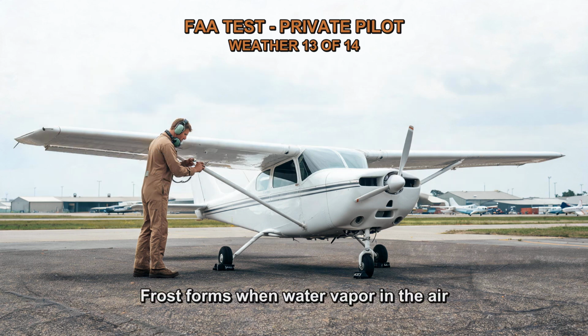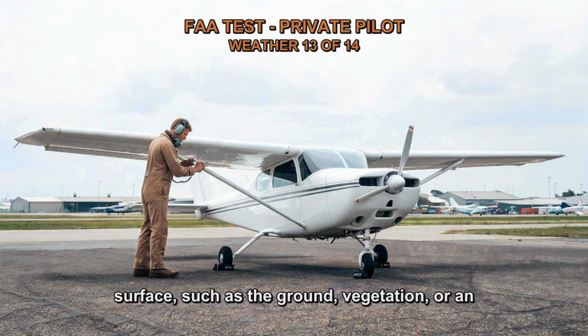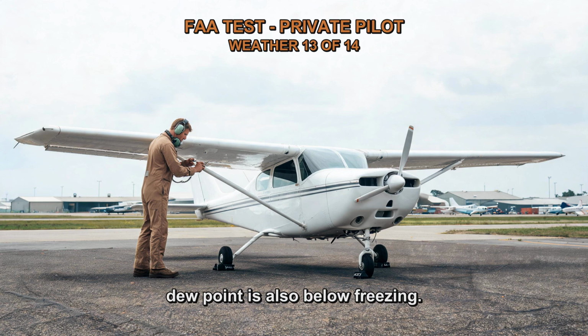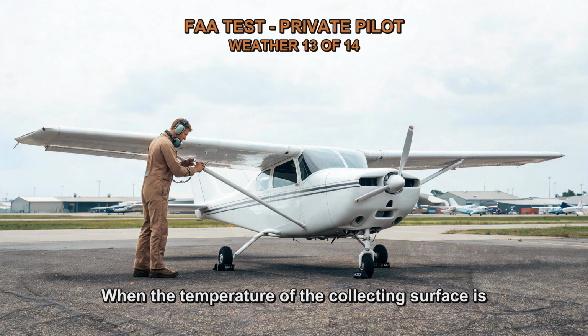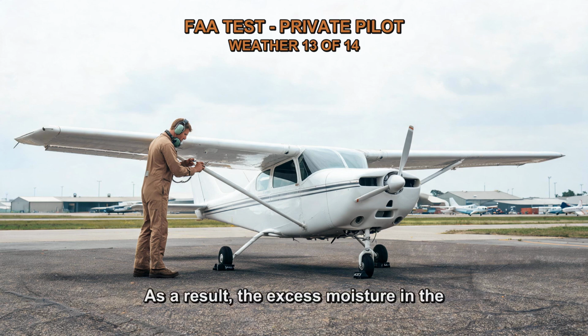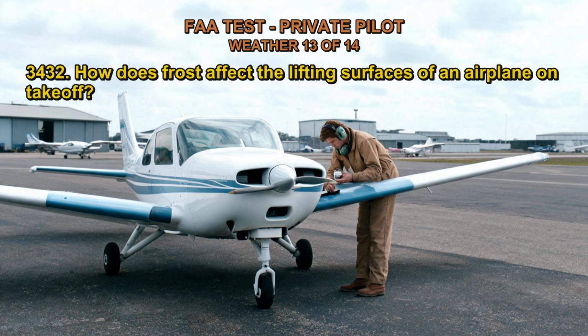Frost forms when water vapor in the air directly transitions from a gas to a solid, deposition, without first becoming a liquid. This occurs when the temperature of the collecting surface, such as the ground, vegetation, or an aircraft, is below freezing and the adjacent air's dew point is also below freezing. When the temperature of the collecting surface is at or below the dew point of the adjacent air, the air becomes saturated and cannot hold as much moisture. As a result, the excess moisture in the air condenses directly onto the surface, forming ice crystals or frost.